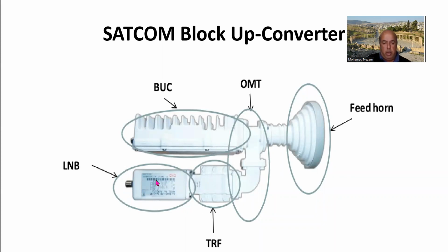So we have covered in the last video a typical design of this KU band low noise block down converter, where we take KU band signals in the receive band, a block of them, and move them down to an IF signal that we could transfer over, in this case using an F-type connector with a coax cable, 75 or 50 ohm, well, in this case, probably 75. So today, let's shift over to this side.